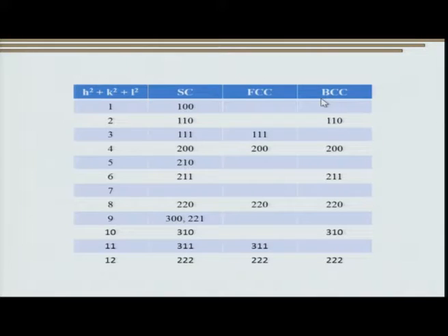Herein we see that the simple cubic material shows a peak rich diffractogram, meaning that we have plenty of peaks in the diffractogram of a material that has simple cubic crystal structure. However, when we go to the face centered cubic structure, we see that the diffractogram is not that heavily populated. Another important thing that we notice is that we do have two peaks which are close and the third peak is far off. This is essentially because of the diffraction condition or the reflectors that are present in an FCC, wherein we do get reflection from 3, 4, 8, 11, 12 and 16.